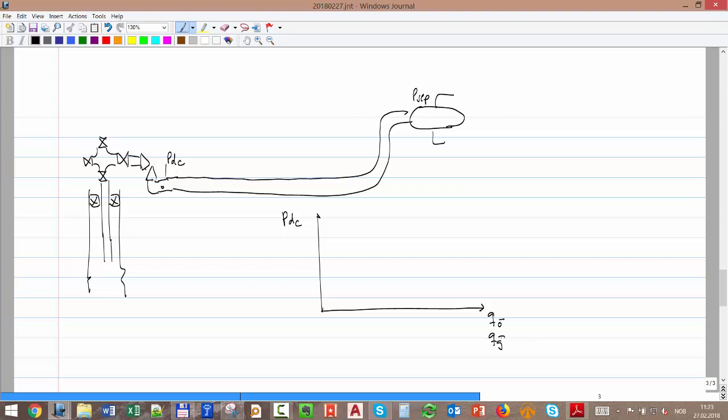That's exactly mode 2, right? I'm fixing the outlet of the pipe, and then I'm calculating the inlet of the pipe. So that will be the required pressure at choke discharge, or we can say at pipeline inlet. And it's going to look, let's say, like that, going up with rate. We will see the curves now.